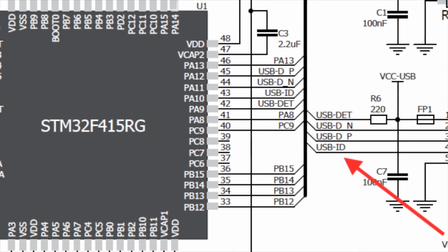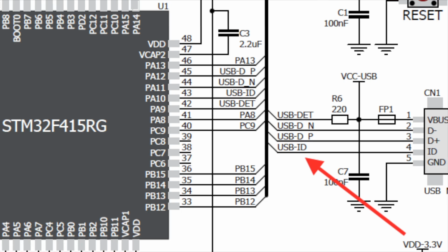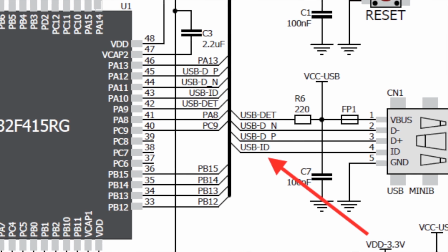Whereas most of the new 32-bit chips coming out, they have native full-speed USB built in, or even native high-speed USB built in, depending on the chips. A lot of them have DFU bootloaders burnt right onto the silicon, so you don't have to worry about bricking them if you do something stupid. You just boot it up into whatever its recovery mode is, then you're back into the DFU bootloader and you can reflash your firmware and then reflash your program or your user files and all that stuff.